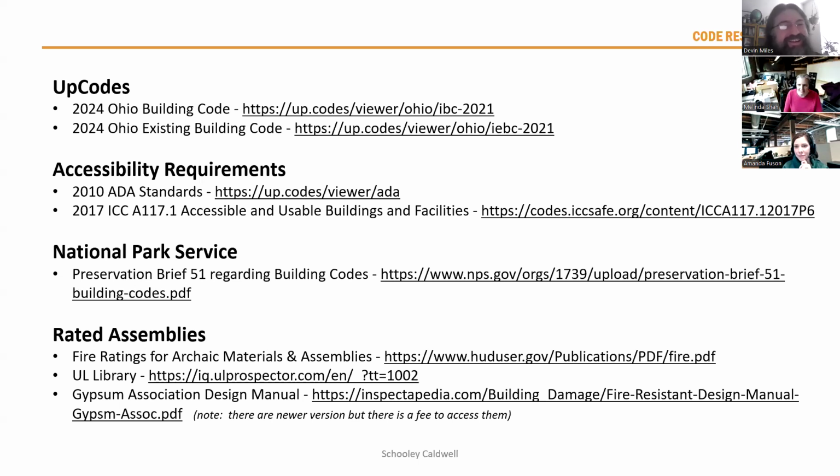Thanks again. Next question: how does being unoccupied for a period of time change the code requirements for renovation? That somewhat depends on your authority having jurisdiction, your local building department. If the building never really lost its occupancy permit, then you should still be able to go back to the occupancy that it originally had. If it was a theater that had gone unused and all the seats had been removed and a bunch of other modifications, it's going to be hard to say that there had been no change in use. If it was just one of your Main Street buildings that had old office space on the upper floors and had just not been used for the last 20 years, but no changes really made to it, that's a different story. It's still that occupancy type. You haven't made any negative improvements to it.